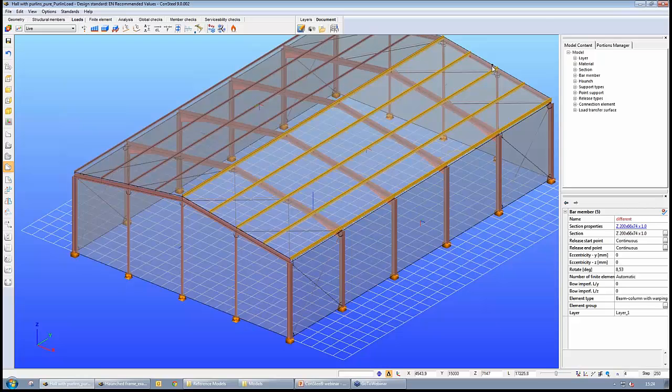So the purlins get usually the surface load through the sheeting, and the beams only through the purlins. But usually the effect is negligible. I just would like to show you that we can do it in this manner, and how we can avoid those situations which come from this special modeling.